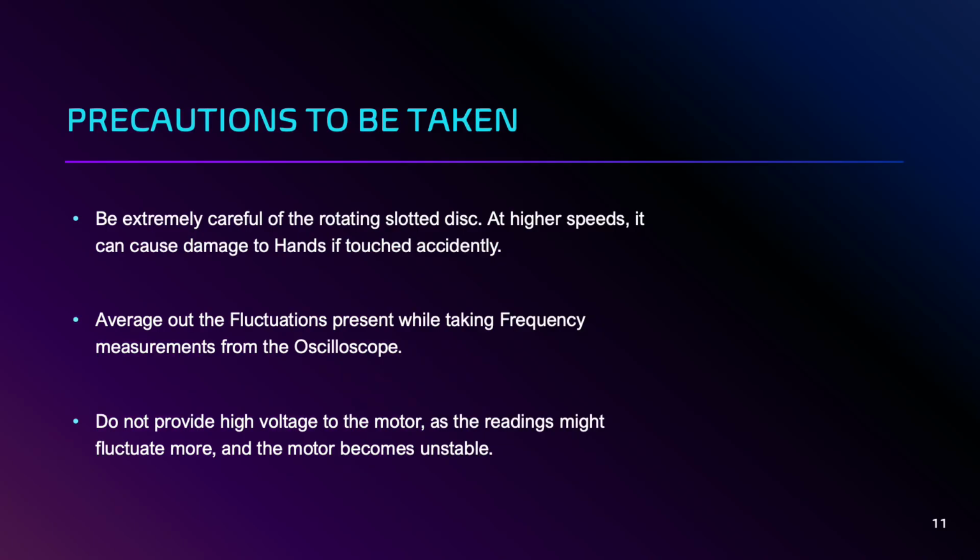Precautions: be extremely careful of the rotating slotted disk at higher speed, it can cause damage. Do not provide high voltage to the motor, as readings might fluctuate more and the motor becomes unstable. Average out the fluctuations present while taking frequency measurements from the oscilloscope.